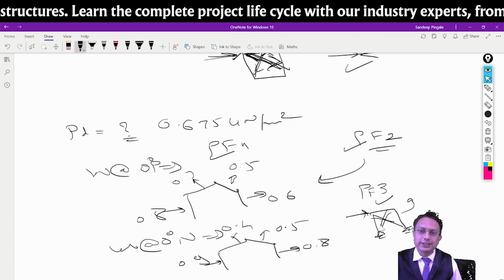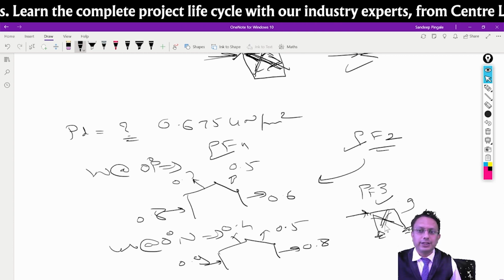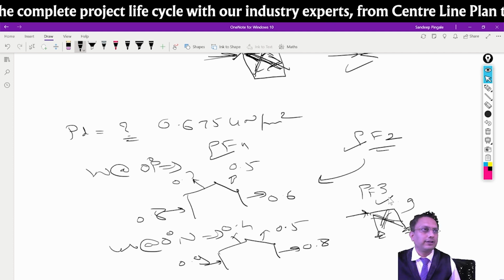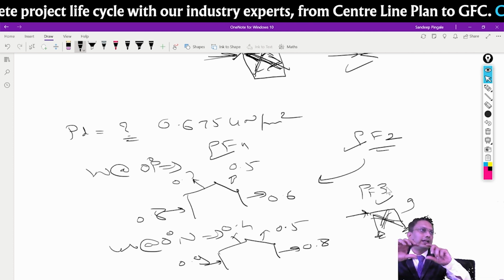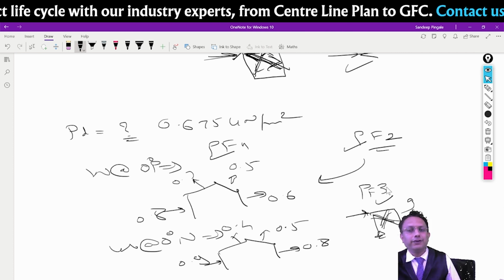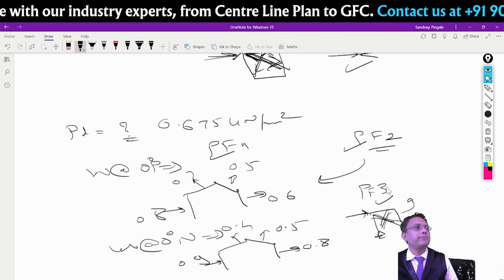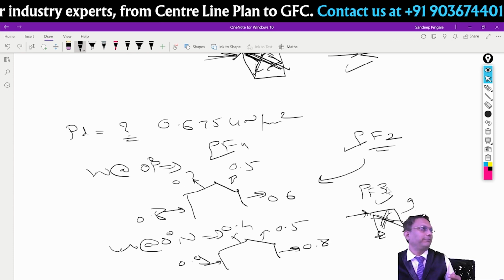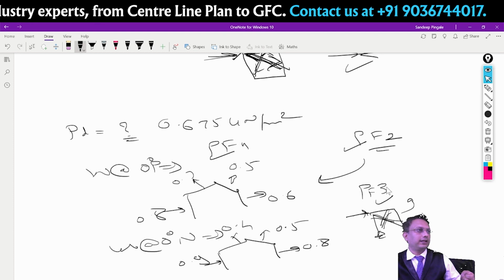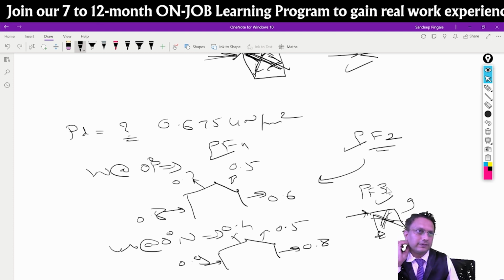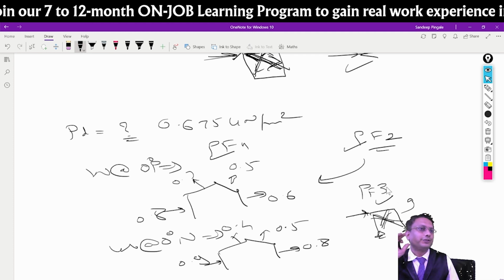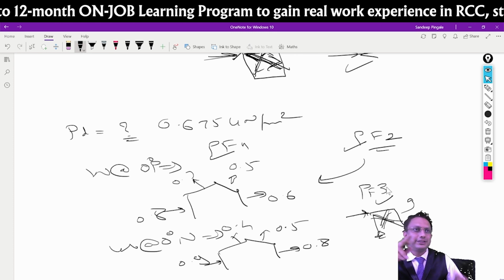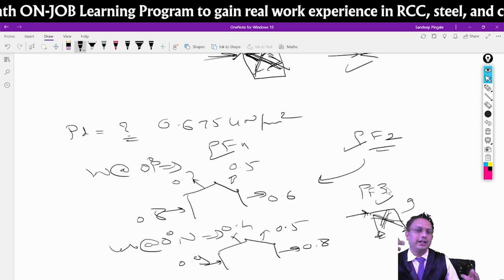And generally, if you ask me, for these ties, if they are under compression or something, you will give channels or angles. If they are under tension, you will give rebars, 16 mm, 20 mm rebar. We will just put bars. Okay, that's how it is. So you give the cross bracing, you design the total frame, and finish it.